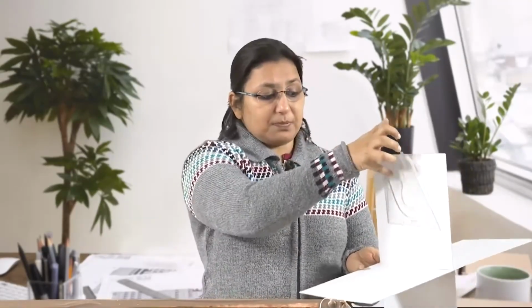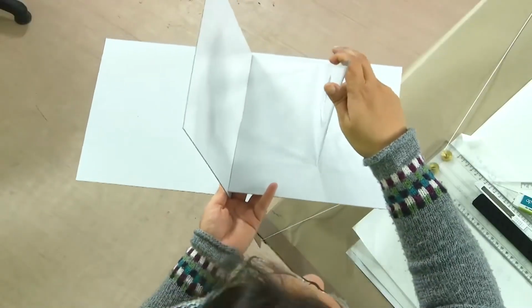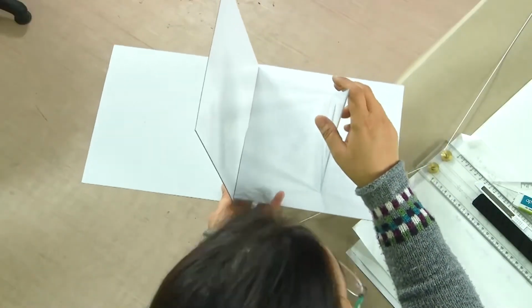What if the plane is perpendicular to the HP but parallel to the VP? What we have here is a triangular plane again, which is parallel to VP and perpendicular to HP. So, in this case what do we see? We see the true shape of this plane projected onto the VP, and in HP we again see a single line, which is exactly the same fundamental which we have been following so far.